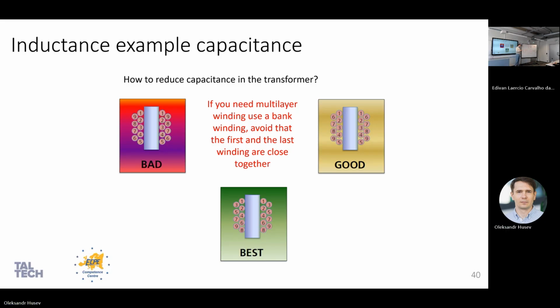So what is better? If you have ZVS condition and you recharge your capacitors by this inductor, which is good, that's no problem. I do recommend to put this. But if you don't have, or you have hard switching condition, better to optimize so that some overshoot may be present, but it's still like 10%, it's not a problem, but you will avoid extra capacitor and extra losses.